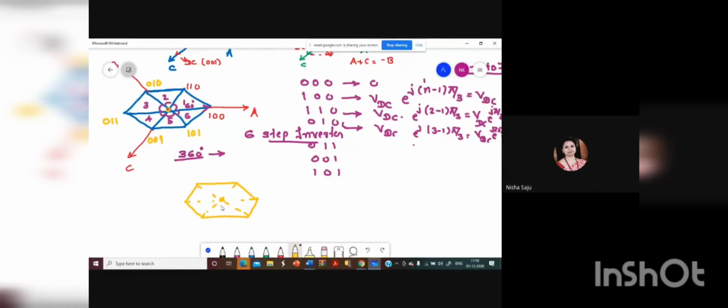You can see here, this is your A phase, this is your B phase, this is your C phase, and then you are having 1, 2, 3, 4, 5, 6 voltage space vectors. So the average variation of the voltage space vector will always move along a circle with uniform velocity. Inside this hexagon, different circles are possible, inscribed at different levels.